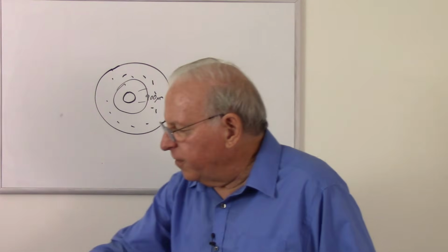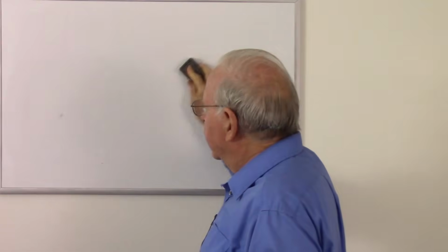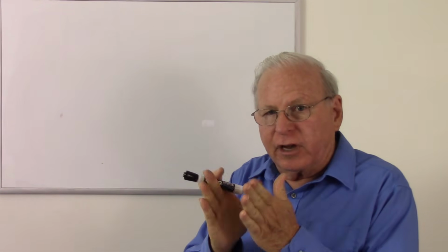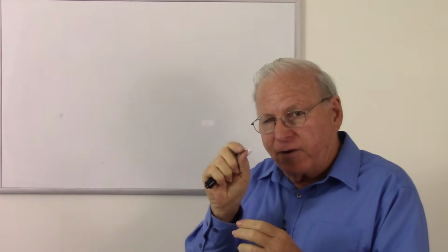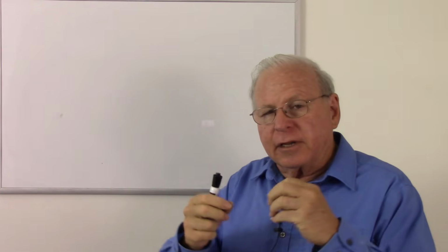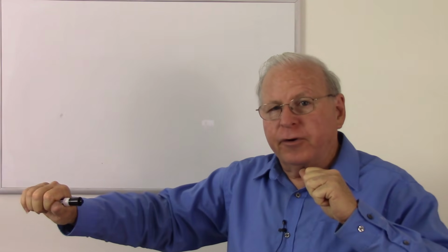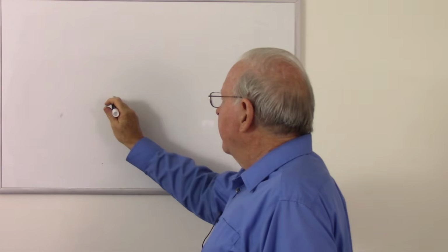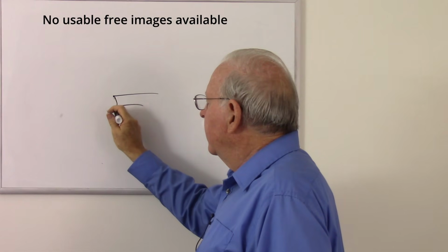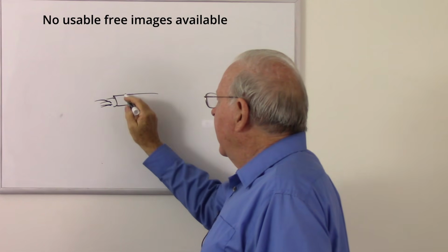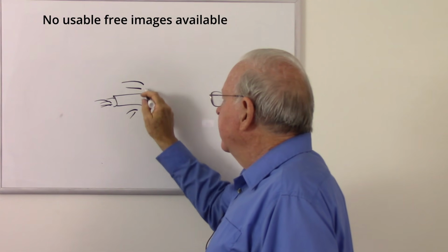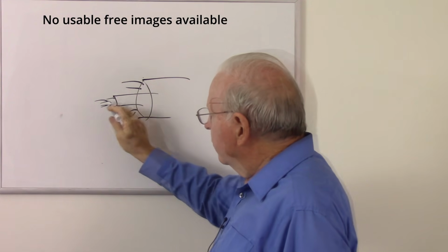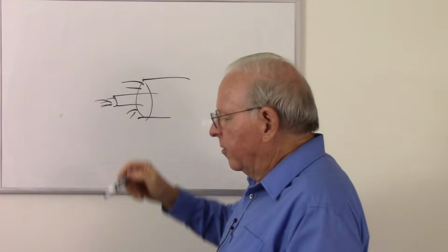And I talked about some other configurations. Loose tube fiber, we cut down all the way to that 250 micron diameter fiber with just the acrylic buffer that's somewhat translucent, very tiny. Those are bundled in a pack in what's called a buffer tube, and that's called loose tube fiber. And here's your buffer tube with your little tiny fibers sticking out, and there'll be some Kevlar around that, and then a jacket around that. And so that's your loose tube with your loose 250 micron fibers inside there.